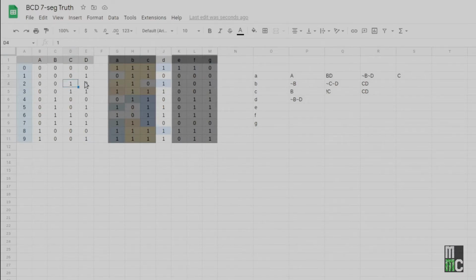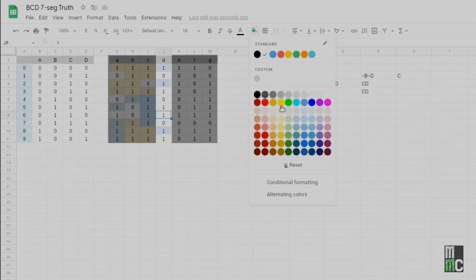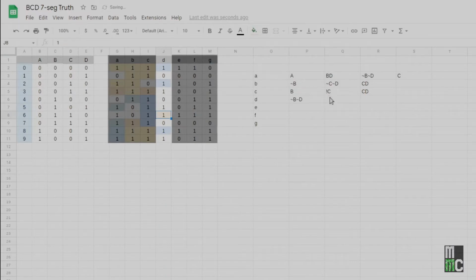But if we keep looking, we will find, at least in this case, you see that when C is on and D is off, we have it here, we have it here, that's that one and this one, and that's the only place where we have C, not D. So that covers 1 that we've already done, so that's going to be C, not D. Like so.